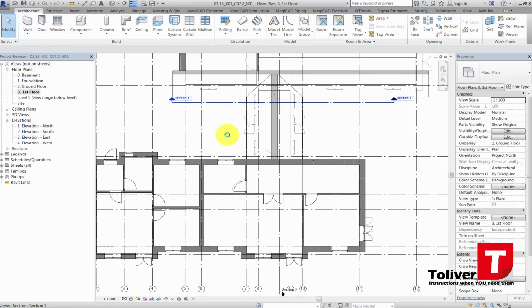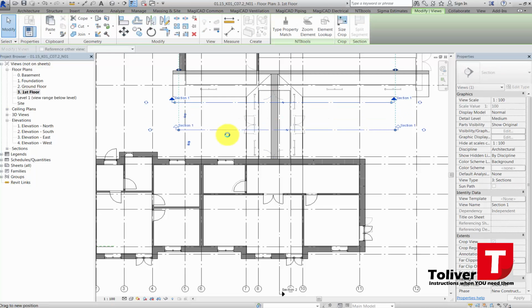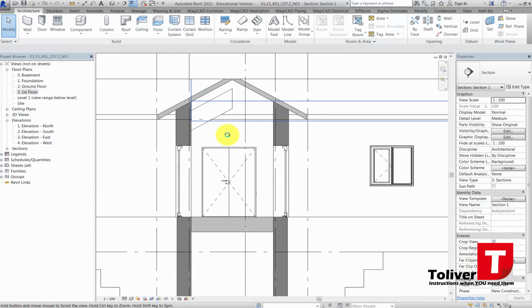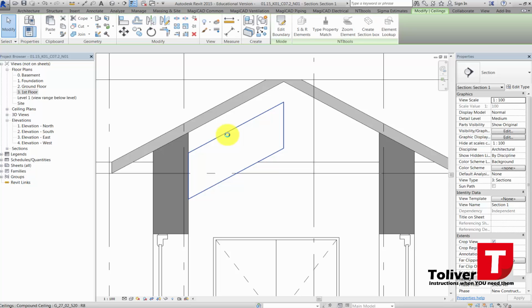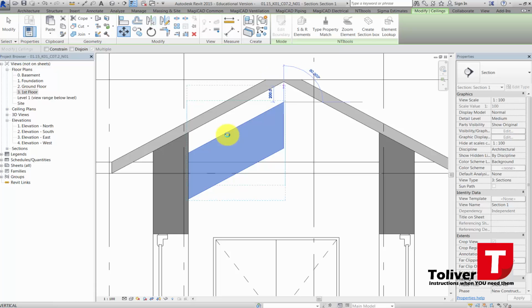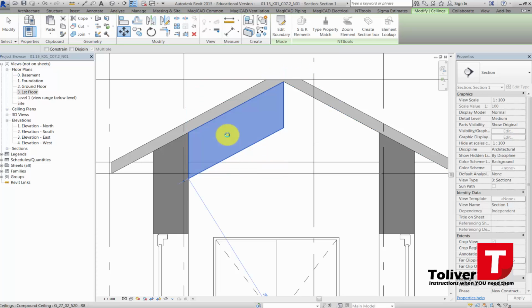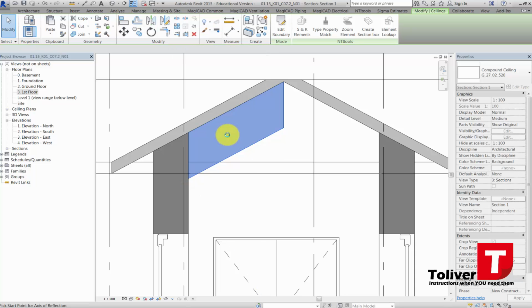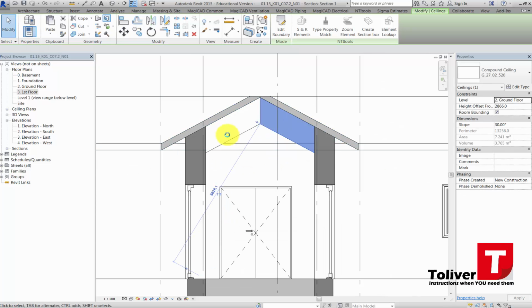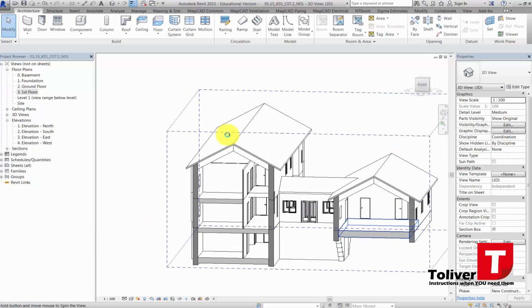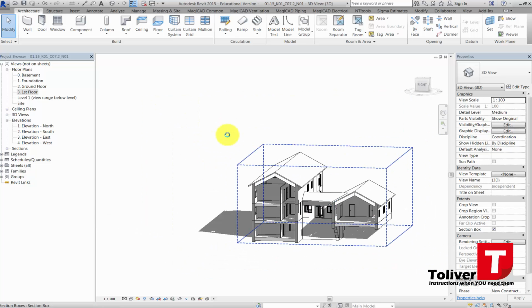So what I'm going to do, I'm going to take my section that I created here, drag it back, go to view, and say, okay, you have it up here. I'm going to take this one, move it, grab that end, move it up to here, then do a draw axis, sorry, DM, from there to there, like that. And then I actually now have my ceiling in all the areas, all the rooms.